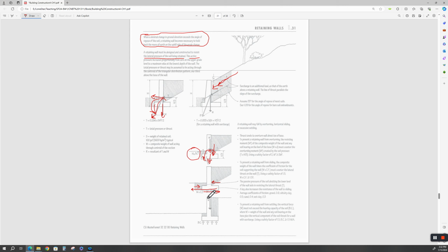And sometimes you'll see some of these footings will have a big cast keyway, like a grade beam down here attached to it, to help key it into the soil, believe it or not. So he's using the term passive pressure. Well, okay, fine. He can use passive. But if this is pushing that way, this is pushing this way.